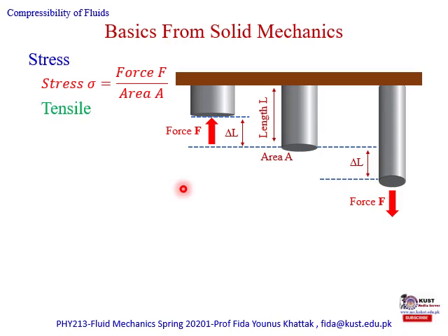Stress could be tensile in nature. Tensile stress is something similar to what we have shown over here, and it causes a change in the length, or it changes the dimension along which the force is applied. Stress could be shear in nature, which is very important in fluid mechanics, where a force is applied not normal to the surface but the force is applied tangential to the surface area.